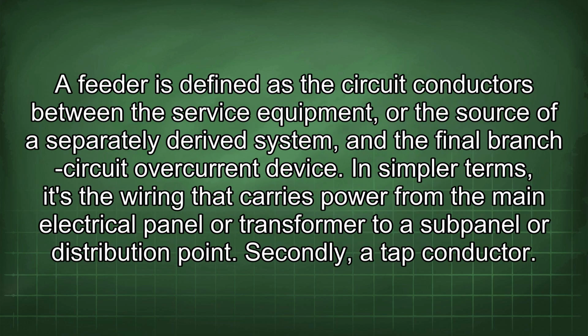A feeder is defined as the circuit conductors between the service equipment or the source of a separately derived system and the final branch circuit overcurrent device. In simpler terms, it's the wiring that carries power from the main electrical panel or transformer to a subpanel or distribution point. Secondly, a tap conductor.